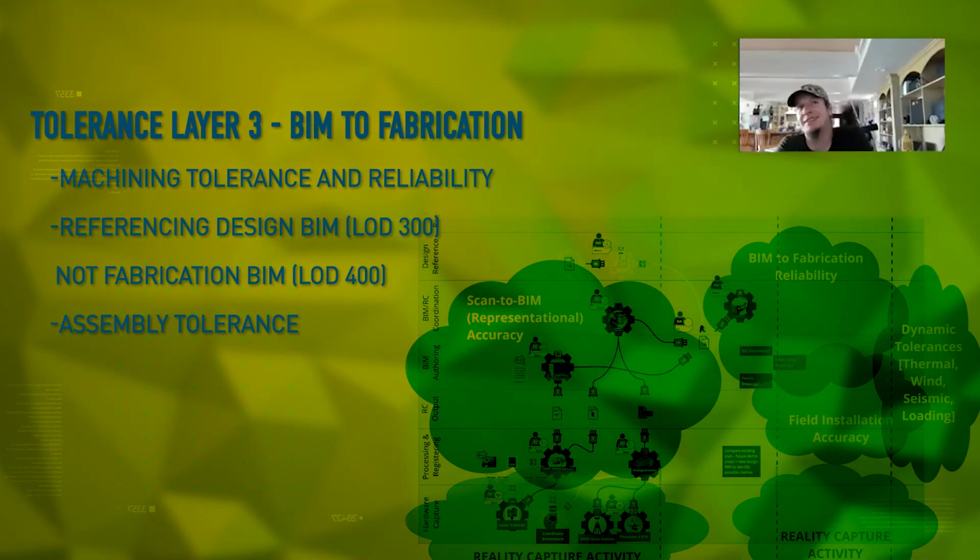Also, sometimes it's making the transition from the design model to the fabrication model. I've seen errors crop up in that, or just things that were fundamentally impossible. A great example is piping elbows in these prefab things. A lot of times the design happens with elbows with no flanges. And then all of a sudden you have a flange system, and now the elbow is slightly shifted, right? It's off by 1/8 of an inch, and now it's conflicting with something else. Reality is both more forgiving and less forgiving in some ways.